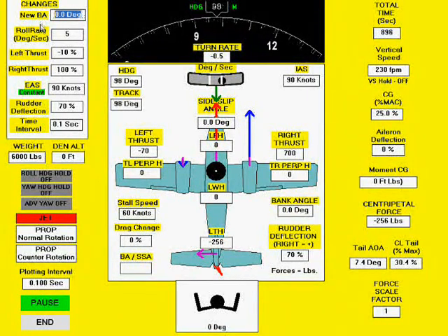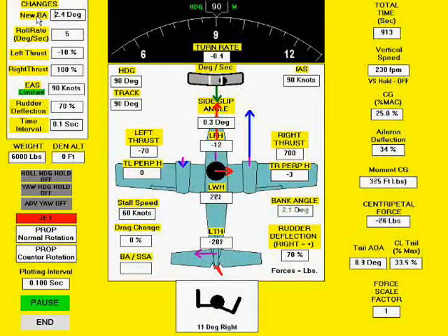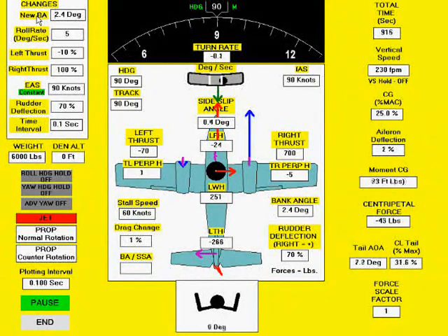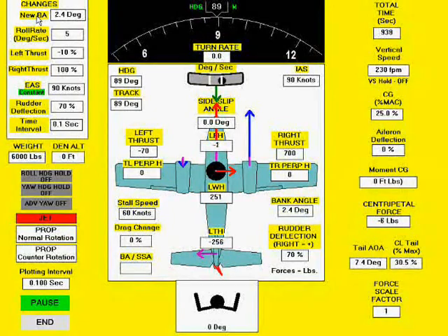Now, since we are turning in this 0 side slip condition, we must establish slightly more than a 2-degree bank angle into the operating engine. We are now flying with a 0 side slip angle and a constant heading while holding right rudder pressure, therefore applying the dead foot dead engine rule. A dead left foot means a dead left engine.